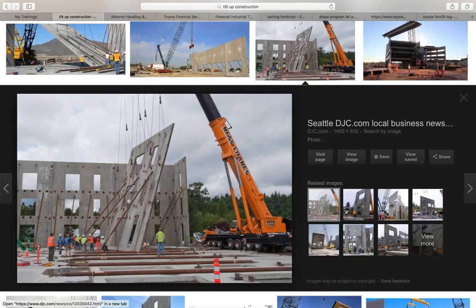when we're cutting with a torch, right? Basically, a welding or cutting operation. We want to make sure we have the appropriate rated lens in there for the operator, for whoever's doing the work, to protect their eyes. Know and observe the proper hand signals for hoisting equipment, like we're talking about, craning and hoisting, forklift. Lift bars or bundles properly, right, to avoid strain. Also, we're going to make sure that we know the location of all of our co-workers, and that we're not putting employees in harm's way.